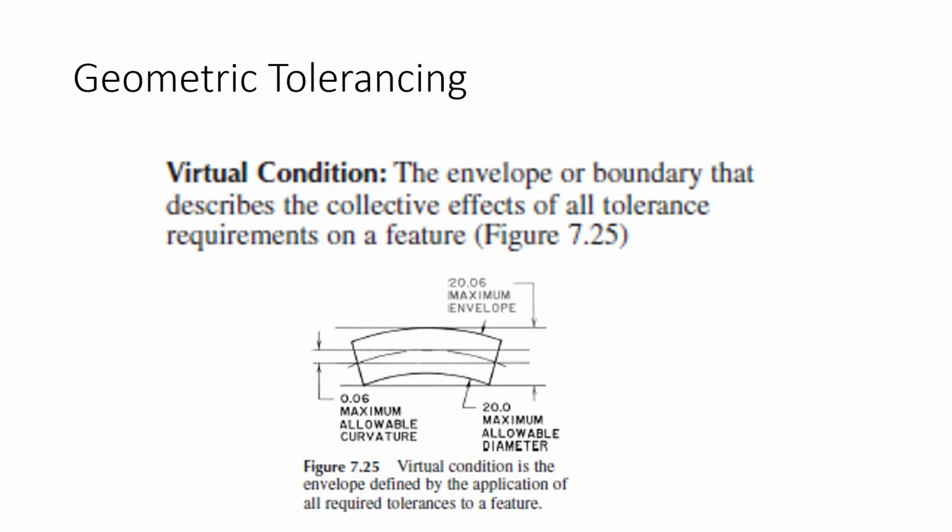Where you see geometric dimensioning and tolerancing primarily is in the fabrication of jigs and fixtures used in production. So we're making these tools with probably 4 times the precision that we expect to get on our output parts, so that all the parts we make with these tools fall within tolerances. So we're really controlling the shape and size of these jigs and fixtures so that I can accurately control the shape and size of my output products. So tooling is where you see this a lot.